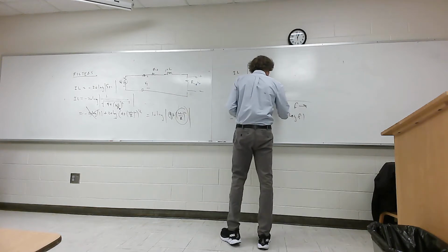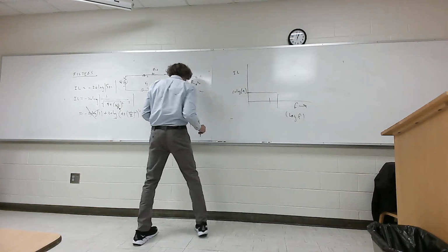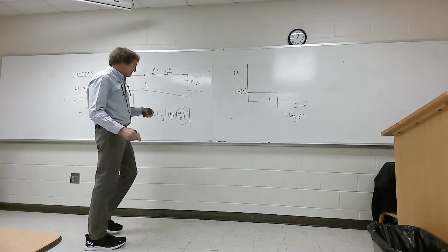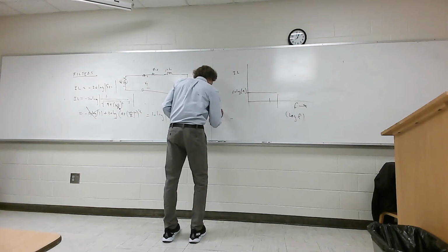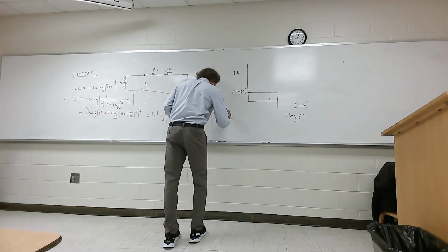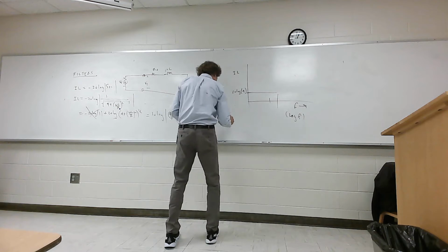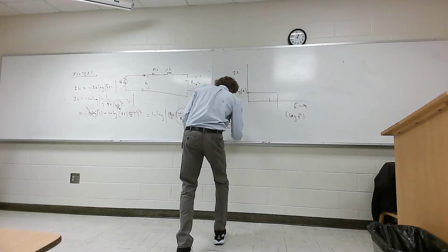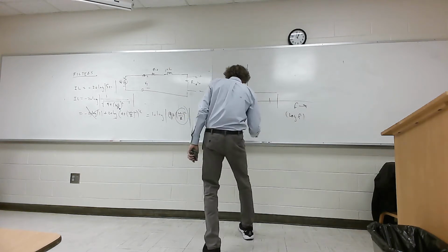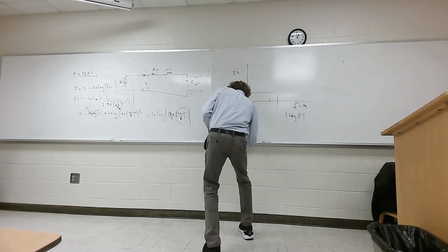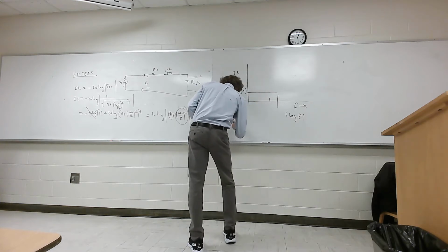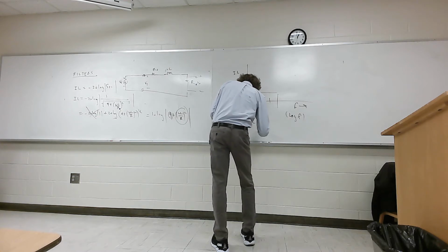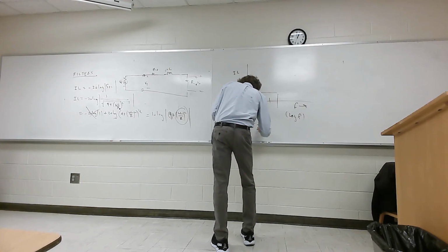It's going to stay there until you hit the frequency where omega L over R equals 2, or omega is equal to 2R over L. And that means F would be equal to, since omega is 2 pi F, R over L pi.